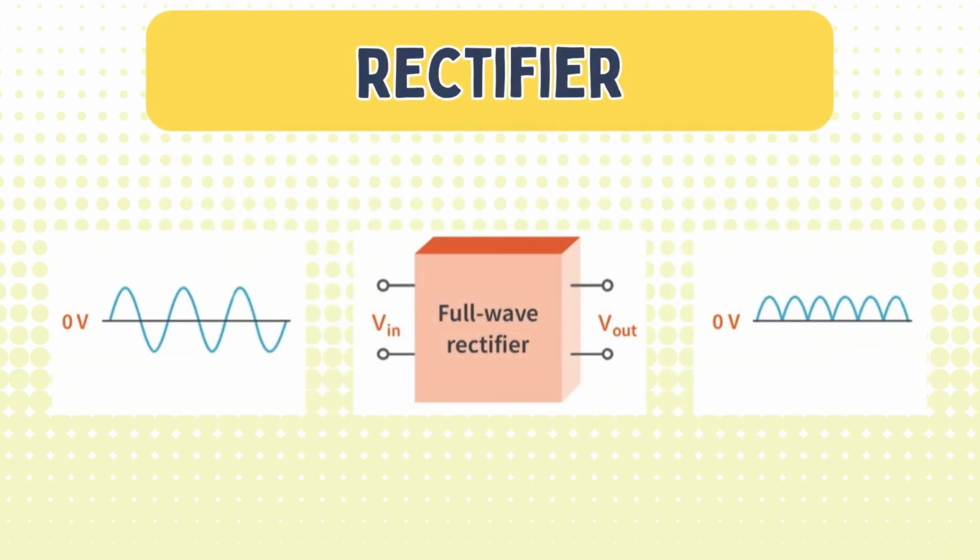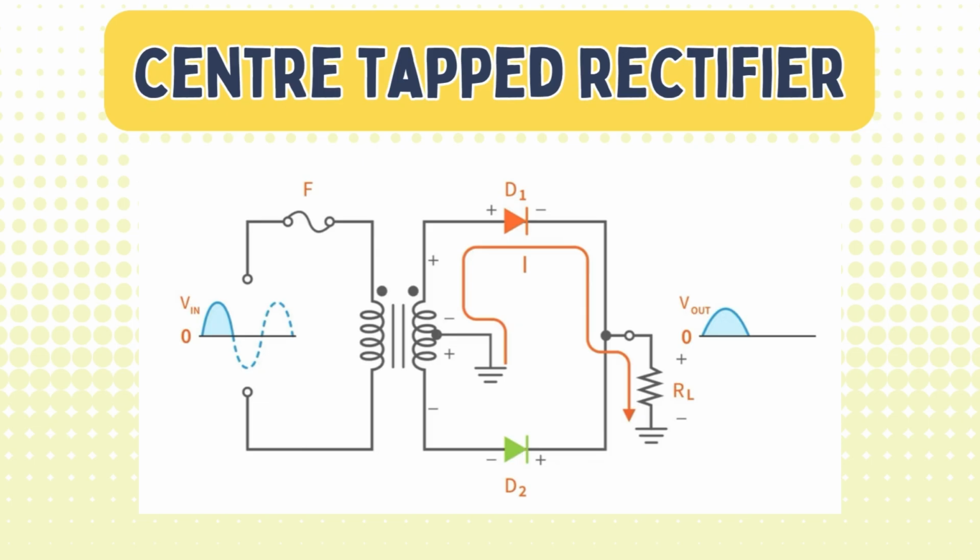For the rectifier, usually we will use a full wave rectifier, since it can rectify 360 degrees of the input, with the output average value and frequency twice that of the half wave rectifier. As we use the center tap type rectifier, I will explain briefly how the mechanism works. The center tap type rectifier only uses 2 diodes and not 4 diodes like the bridge type rectifier.